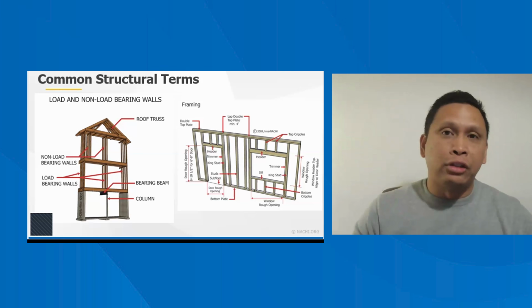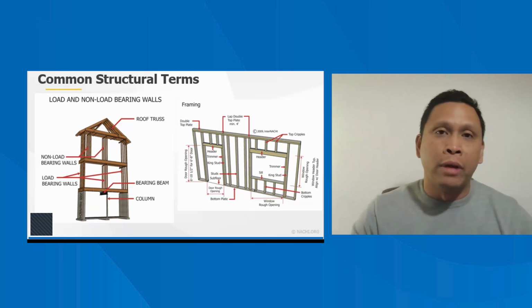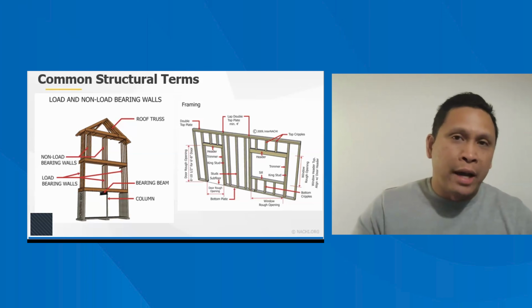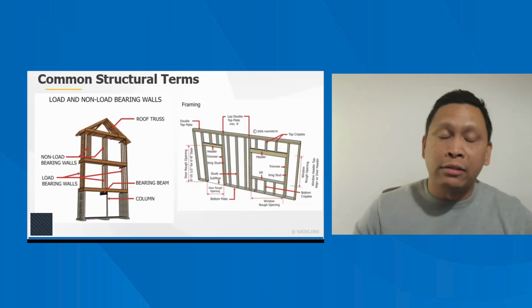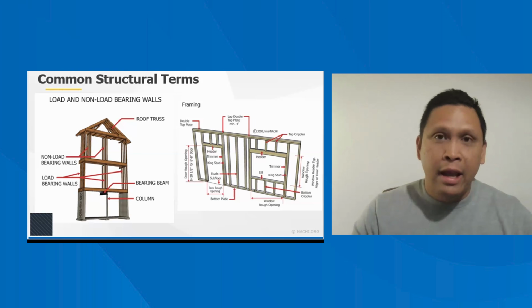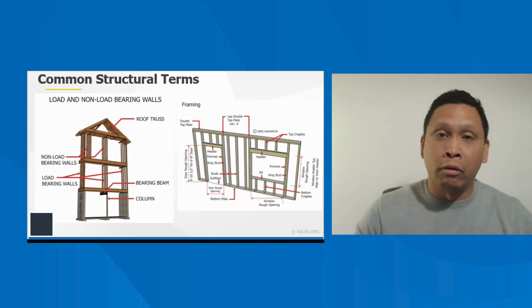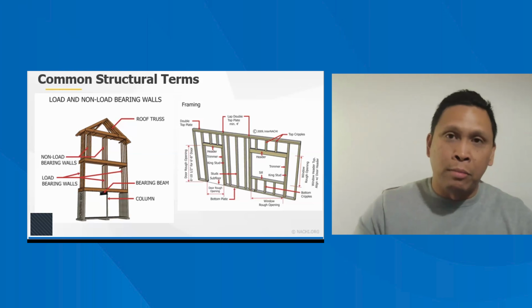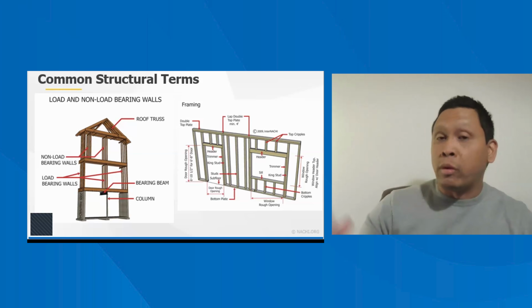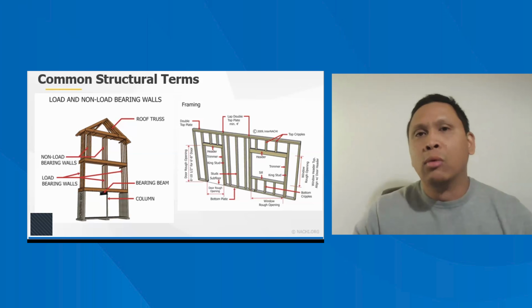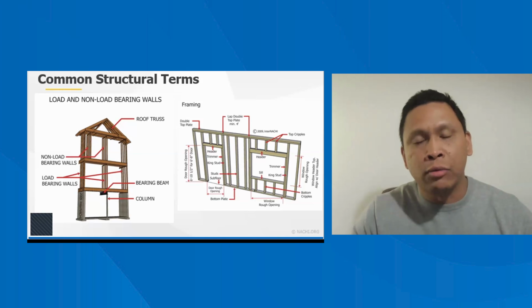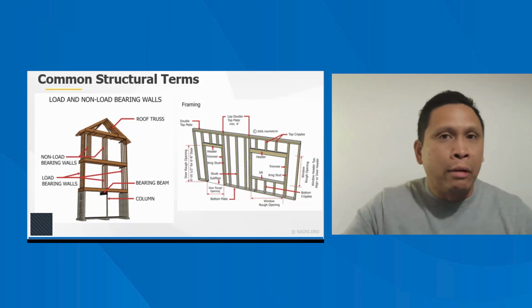But then at some point in that inspection, something brings me back into that dining room, into that corner for whatever reason. And then all of a sudden, when I'm taking my time because I'm just standing in that area trying to note something else in the report, I look down and I think to myself, huh, the floor is really not all that level here, even if it's a smaller section of the floor. And then that's when you start to pause and think, wasn't this the area where I found and noted a crack on the foundation on the outside? Oh yes, it was. This was the same exact window that was hard for me to open and close, that I also noted in the report.